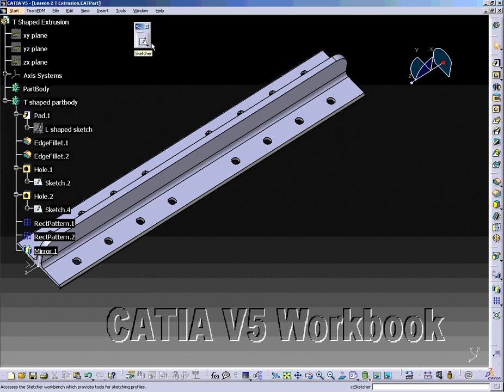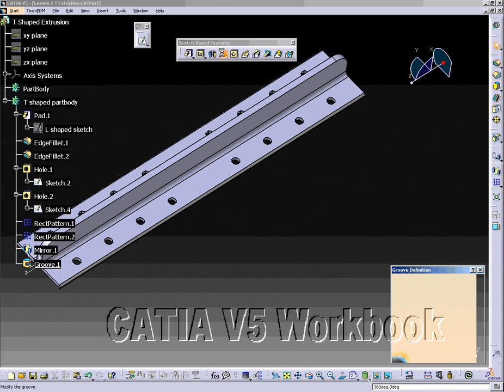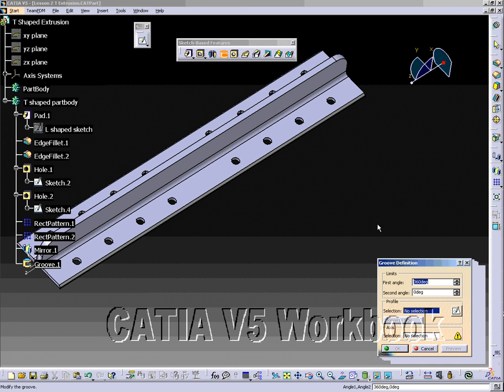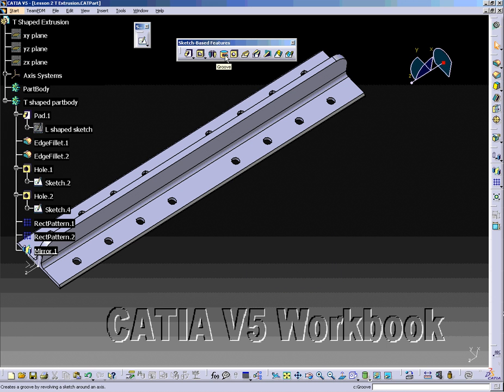The Sketch Base Feature toolbar consists of the Shaft tool. This creates a solid by revolving a sketch around an axis. The Shaft tool requires the Axis tool found in the Sketcher workbench to define the axis of rotation. The Groove tool creates a groove in an existing solid by revolving a sketch around an axis.